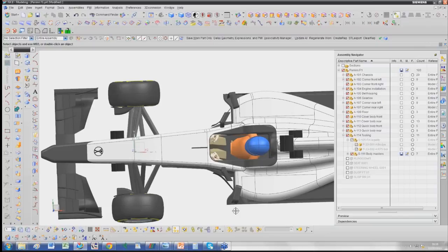Okay, that's a question I can answer. Alan asked, why did you set for boundary conditions inlet, front of the car, and outlet behind the car? Yes, Alan. I think you've checked out the simulation, and the reason is that you want the flow to come in before the car, you know, and in the wind tunnel, also the inlet would be before the car and the outlet behind the car.